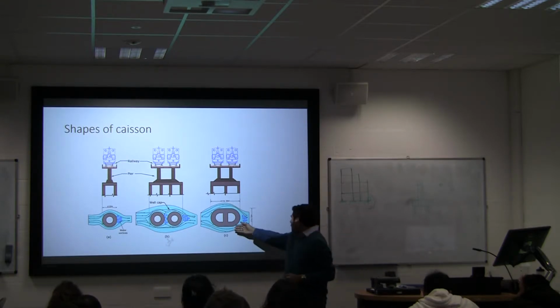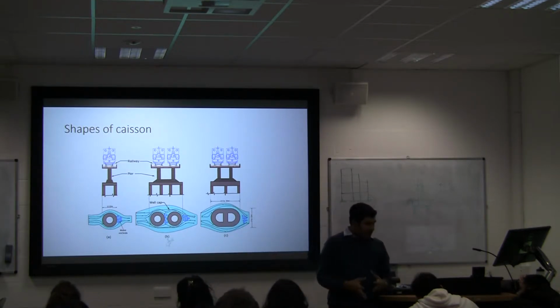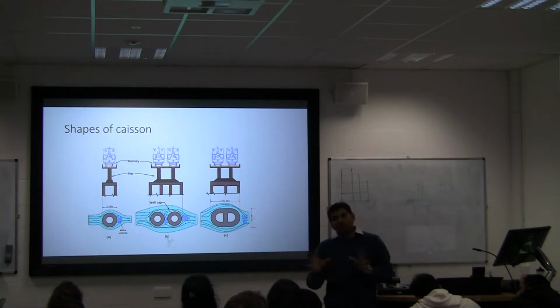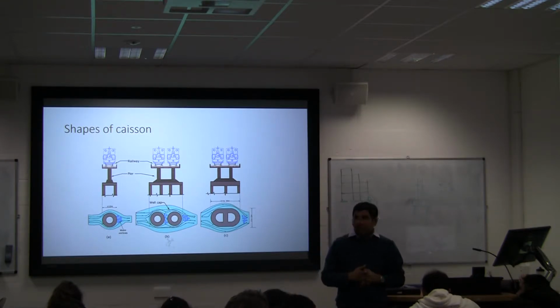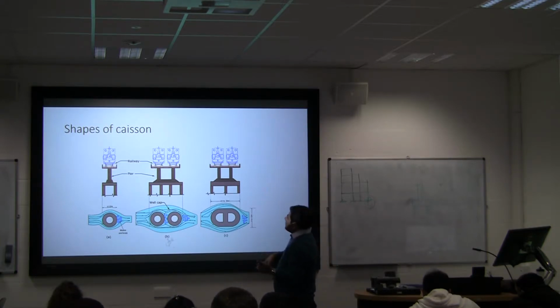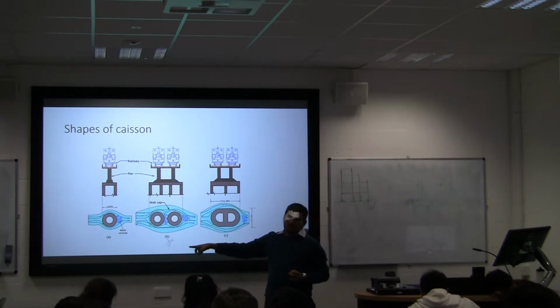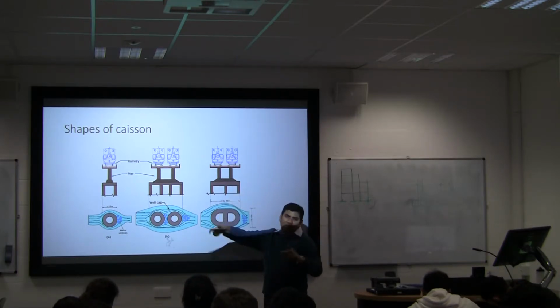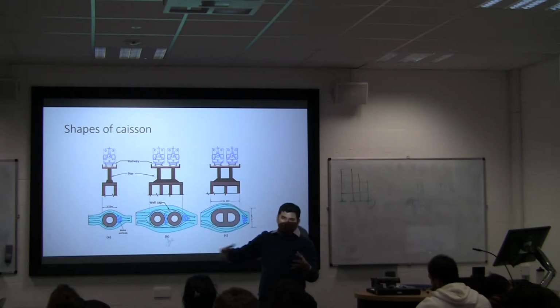If you do the double D, you have a higher capex cost, meaning a higher cost to install it, but once done, you are more or less good for many years, so lower maintenance cost. Okay? And also, the large sections will easily take quite a bit of eccentricity of loads. And if you have two, you have to make them compatible, right?